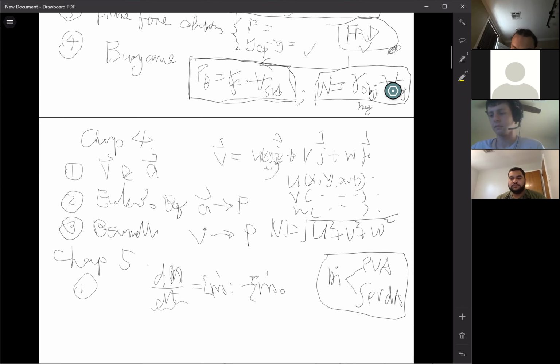So if possible, I give you a non-uniform velocity field, and you need to do the integration. I assigned homework problems for many different surfaces to calculate non-uniform flow rates. Look at how to do those dA integrations for different shapes. That's something you need to know too. But if it's a uniform velocity, then it's easier. We often see problems to calculate the velocity based on flow rate in equal to flow rate out.